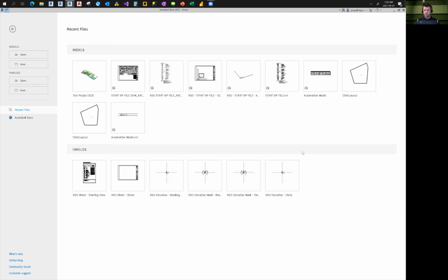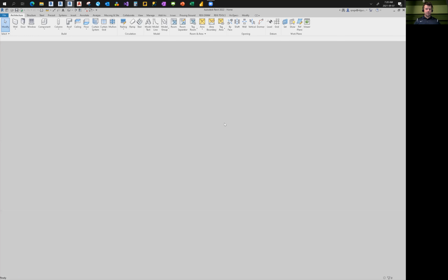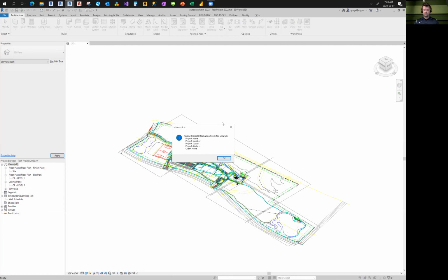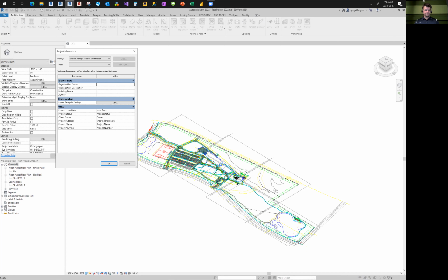So I kind of took a dive into extensible storage within the Revit API, and also just seeing how we can probably manage the layers a little bit better. So what we're going to see here today is how we can save layer states now within the document, but then we can also apply those layer states, or import instance properties, from view to view without using a view template or applying a view template, etc.